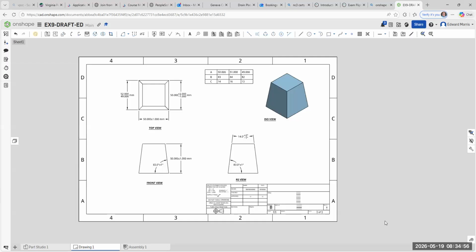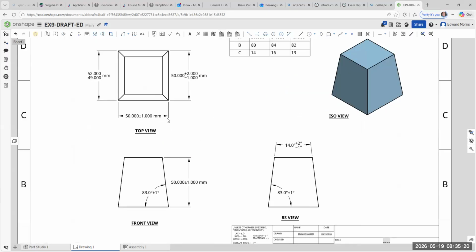We came in here and I said, let's practice dimensioning today. If you were to turn this in for a drawing, I'd probably give you a bad grade on it because I don't need that many dimensions. I was not worried about the number of dimensions. I was worried about, do you know how to use the tolerance tool? And you do. You should now. This is symmetrical. This is deviation. These are limits. They all mean the same thing.